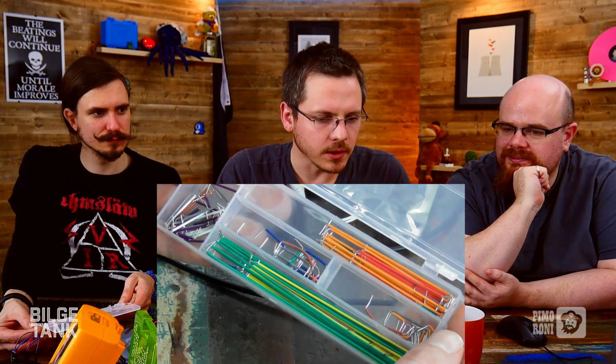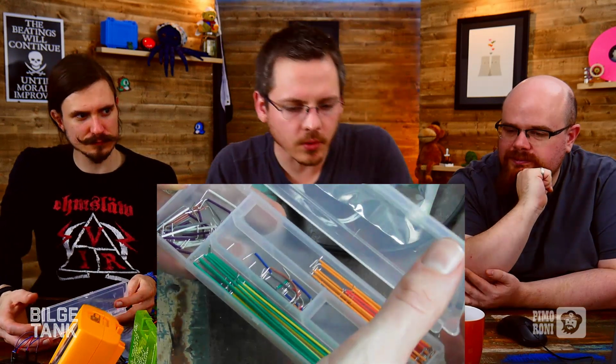And the other thing was that when you are doing breadboarding, always have a nice pair of thin nose pliers, because when you get a component and you trim the leads down, being able to just turn a leg like that is so much easier than bending them by hand. Sometimes the breadboard holes can be quite resistant, and when you're pushing something in, you'll end up bending the leads rather than pushing it in. So I tend to use those pliers to grab the leg and push it into the breadboard.